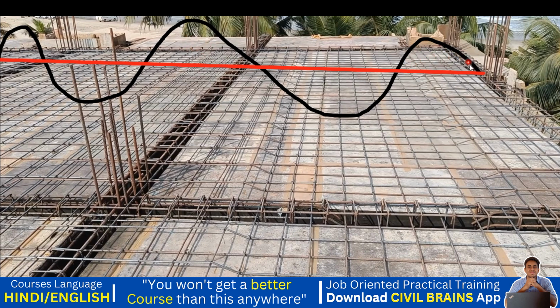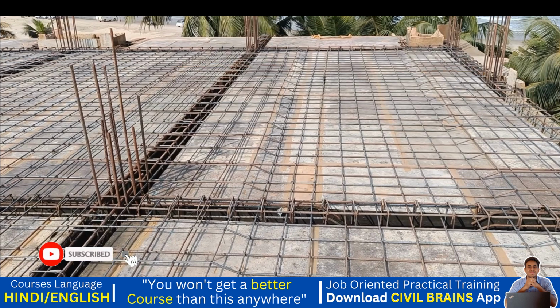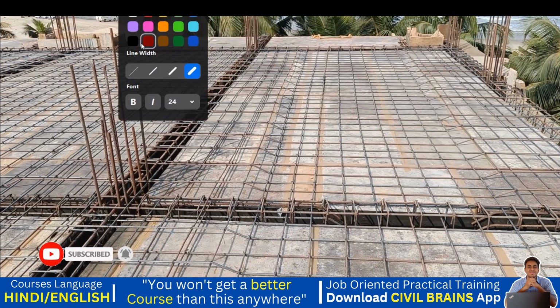That means your slab will try to lift up in this portion. Wherever I have shown the line below the red line, that is this part, this is my sagging bending moment. That means in this particular portion my slab is going to sag, that is, going to come down. Similarly here also. I hope this much of the concept is clear. Now this is the overall slab I have explained, but I'll take it out and explain it for only one particular slab, and we'll try to understand that in a better way.